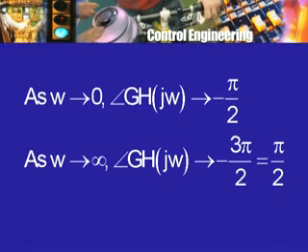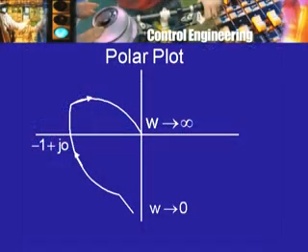All right. So, with these two items of information about the gain and the phase shift, we are ready to sketch the polar plot. At low frequencies, the gain is very high, but the phase shift is minus 90 degrees minus a small amount. So, it will start off, let us say, somewhere here. For very high frequencies, the gain is very low, so I am very close to the origin, but the phase shift is almost minus 270 degrees, and therefore, the shape of the polar plot is like what I had drawn earlier.